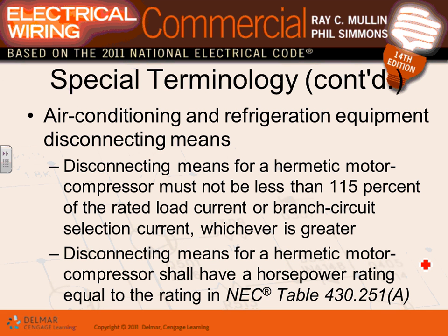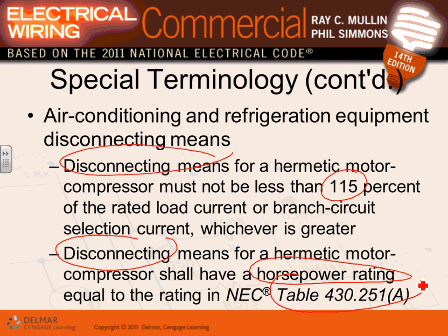We talked about the disconnects, guys. When you size your disconnect, here's your multiplier, 1.25. Your disconnect also has to be horsepower rated, and for this, you have to go to this table. So when you have a disconnect, it's not enough to say 100 amp disconnect. 100 amp, 50 horsepower. So if you are to open it under load, it's not going to explode in your face. These two guys, sizing disconnects, amp-wise as well as horsepower-wise.